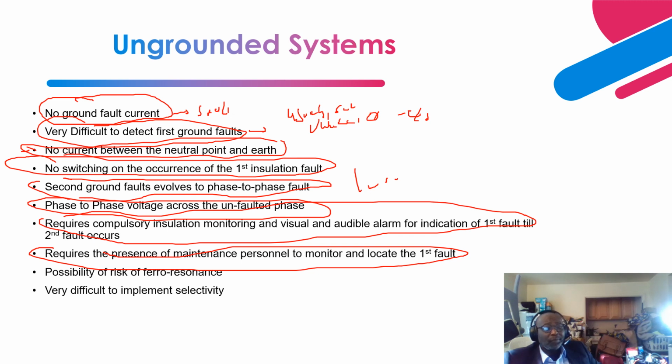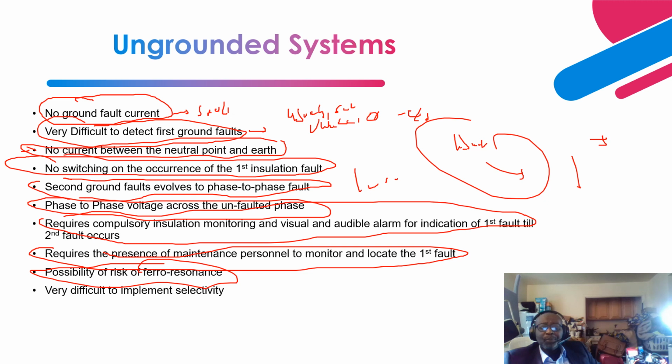Then there's also the possibility of ferroresonance. The inductance of the equipment, let's say a transformer, and the stray capacitance, and also if there is a capacitor bank at a facility in close proximity to this equipment, then there's the possibility of a resonance being formed. Also if a cable is connected to this equipment, the cable insulation system forms capacitance, and that can result in ferroresonance activity.